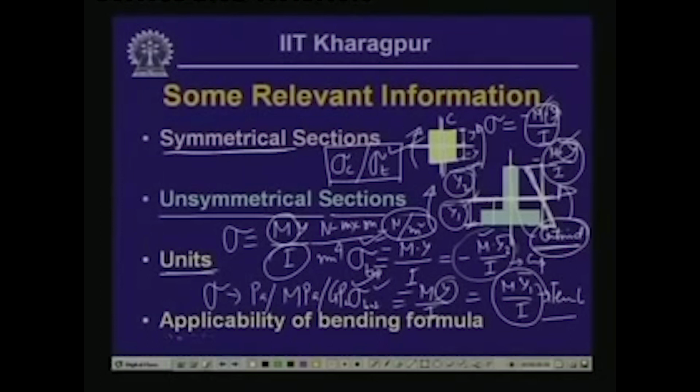Now, lastly, the most important thing is the applicability of this bending formula. If you remember, while deriving this bending equation, we had assumed that the segment of the beam is subjected to pure bending. In normal situations, when a beam is subjected to loading, it will be subjected to bending moment, and in some zones there could be bending moment associated with shear force.